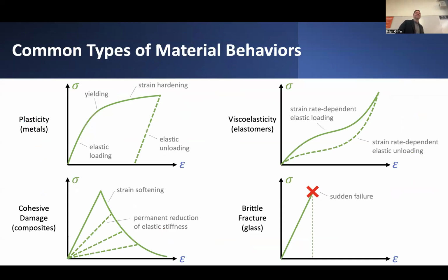Okay, so that's orthotropic elasticity, but enough with elastic behavior, right? We were really interested in nonlinear behavior. And more specifically, there are a few types of nonlinear material behavior that I might point to as specific examples of behaviors of engineering materials that we care about. One good example is plasticity, where we load the material within some reasonable range of stresses, and then when we reach some critical threshold, the material appears to lose some of its stiffness. As we continue to load it, it seems like it's lost most of its stiffness. Maybe it still retains a little bit of stiffness.